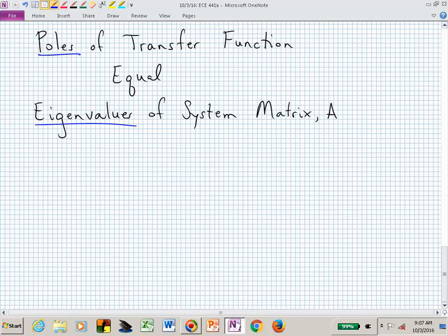I'm sort of asking for chair number 1, but I'm not wanting it yet in that form, am I? I'm actually asking for A, B, C, and D. So I'm just asking you, give me A, B, C, and D in the state space representation form. Meaning, let's write it as the time rate of change of our vector x is equal to the system matrix A times x of t, plus the input matrix B times u of t, and y of t is equal to C x of t.